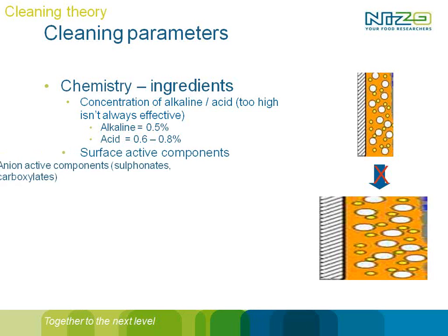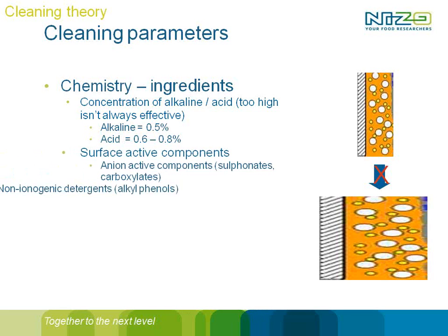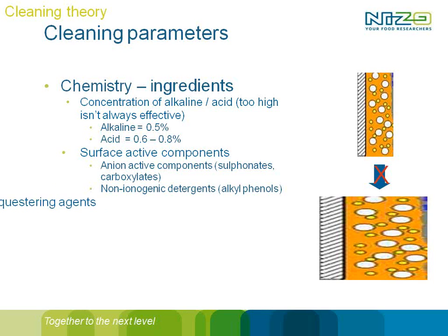In addition to, let's say, the standard alkaline and acid, you do have other components, for example, surface active components that will make it easier to attach to the fouling. You do have what we call sequestering agents that can bind specifically to, for example, calcium. EDTA is a very well-known example of that.